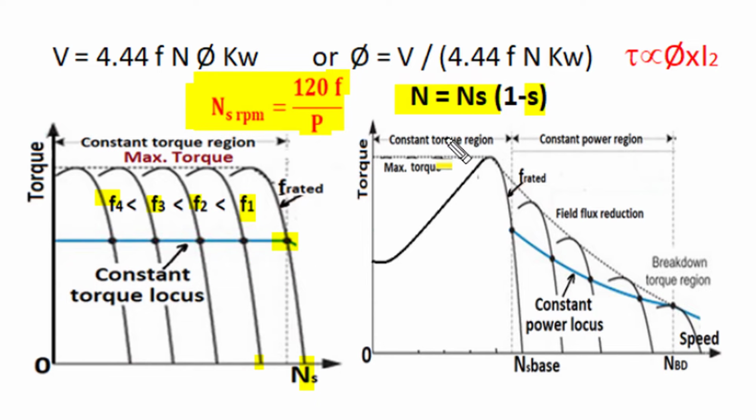But during this operation, we also reduce stator applied voltage in the same proportion as applied frequency and maintain a constant V to F ratio, and that maintains constant air gap flux and the rotor maximum current capability produces the torque capability of the motor. So during this reduced frequency operation to get reduced speed, when voltage and frequency are simultaneously reduced in the same proportion, the maximum torque capability of the induction motor remains the same, and this operation of speed reduction with constant V/F ratio is known as constant torque control of induction motor.